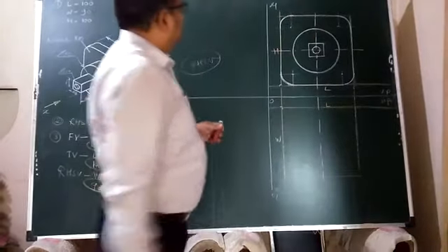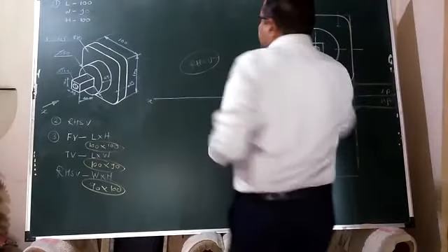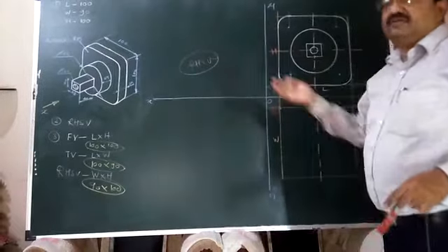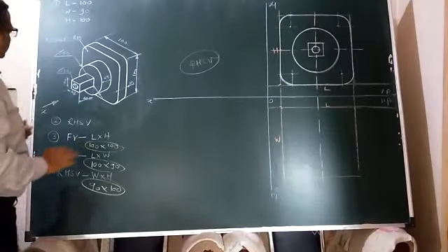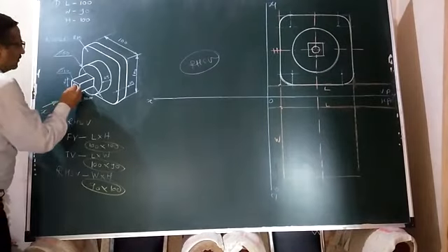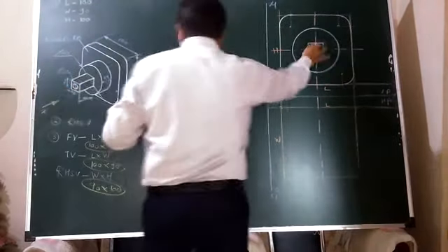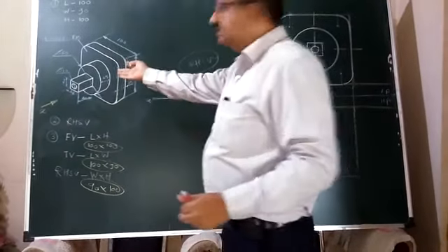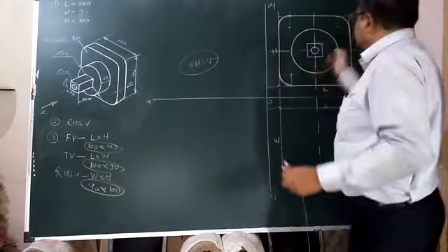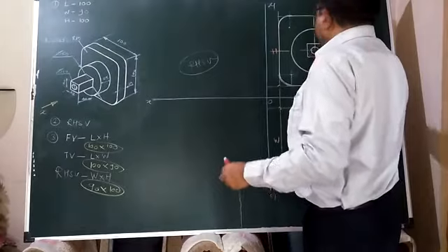Okay, so this much part in this way only, the front view or elevation will be appearing. Just see, is anything left over? Nothing, I think so. Centrally, this 10 mm diameter hole that I have shown here. About that, this square appearing as a rhombus, because it is 3D, but actually in 2D it is a square 20 by 20.